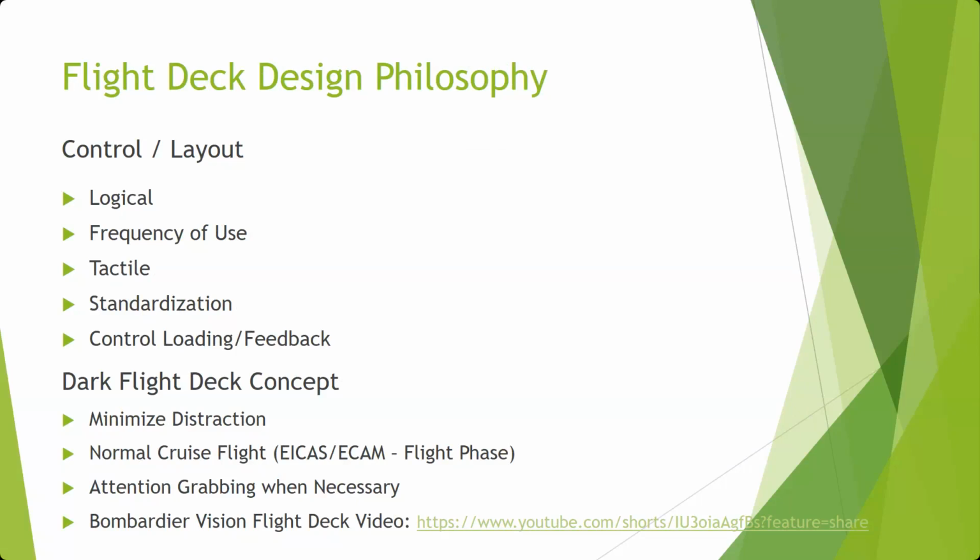Switches, and I mentioned this to some of the groups in the 727. Which way do the switches go? How do we turn a switch on an overhead panel? Push it forward. So don't think about it as up and down. If you do think about it as up and down, you're going the wrong direction. You're pushing it forward to turn something on. You're pulling it back to shut down. Think about how the throttles work. You push forward to make the airplane go. You pull back to make the airplane stop. So they do the same thing with switches.